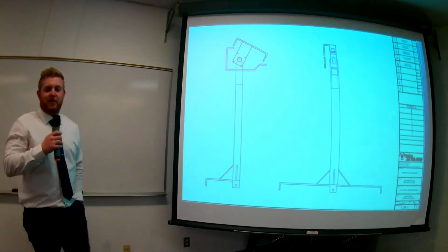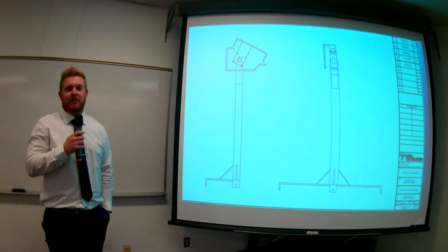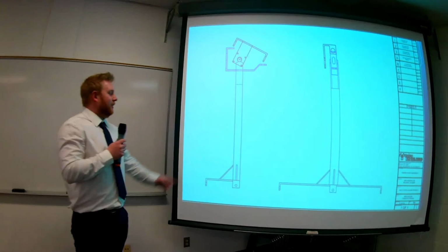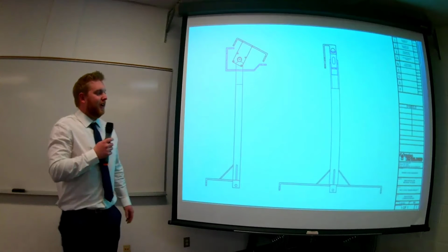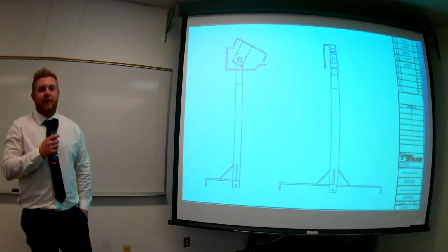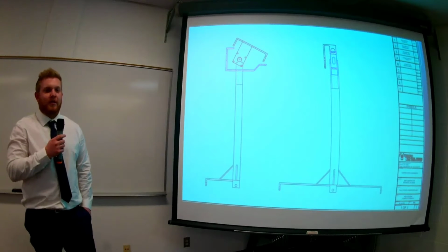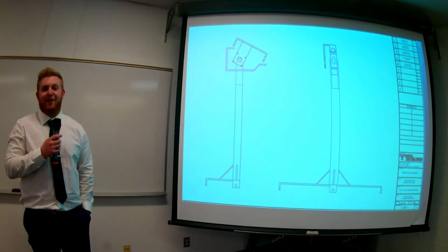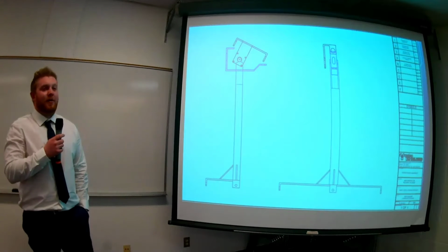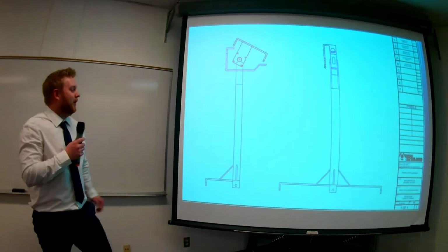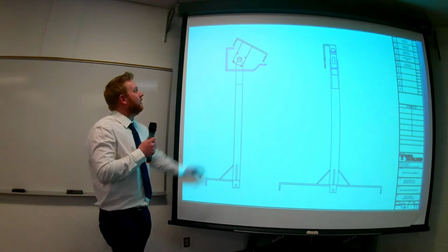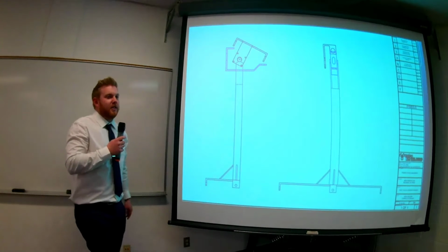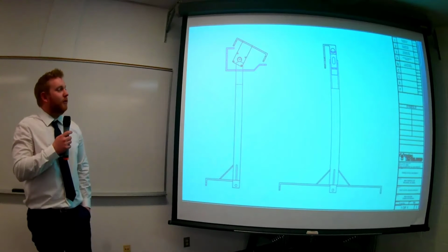I know it might be a little difficult to see online, but a major part of my part of the presentation was drawings. This is the rod holder that I designed and then had Certified Sheet Metal fabricate for us, which they donated for our senior project, so I thank them. It was definitely with flaws. We had to modify it, but as it was donated, we had to make it work so they didn't have to do it again. As it sits, it's about 24 inches tall. And our motor mounts right here. We put an Allen wrench inside the reel, so that's our one gear for the reel to spin.